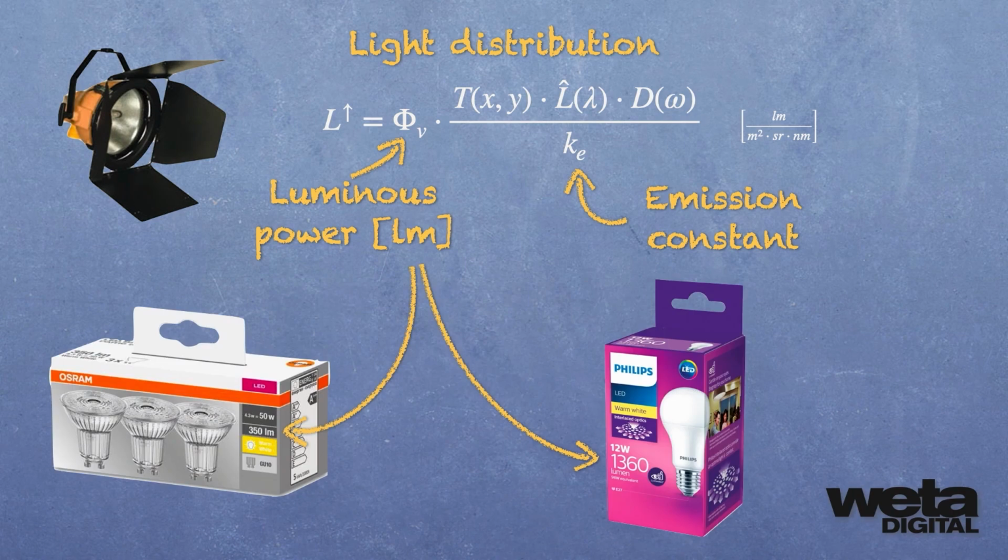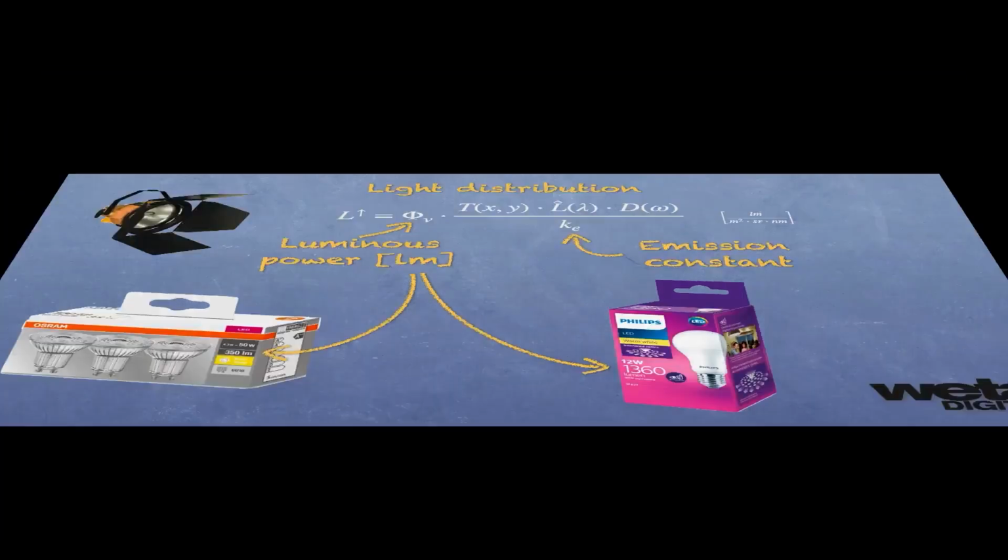You can see that the brightness is called luminous power and is measured in lumens. You might be surprised it's not measured in watts. This is because the different kind of light sources show fairly different levels of efficiency in turning electrical energy into light. For example, tungsten-based emitters are mostly emitting in the infrared band, where we cannot see. Since household lights have moved to LED technology, packaging for everyday light bulbs also displays the brightness of the lamps in lumens, because that way different bulbs can be compared more easily.